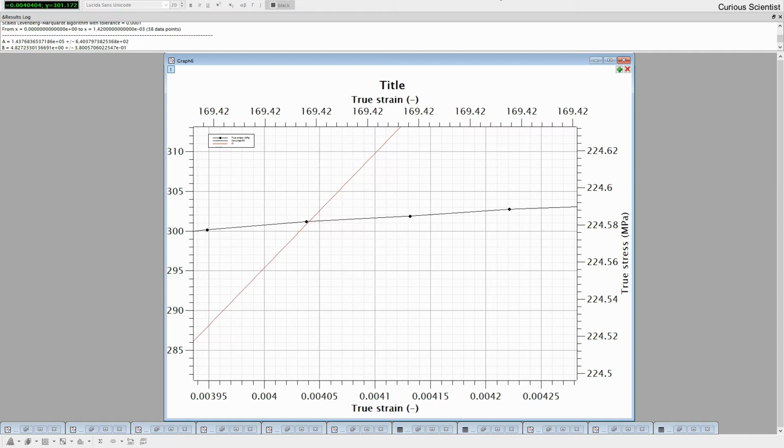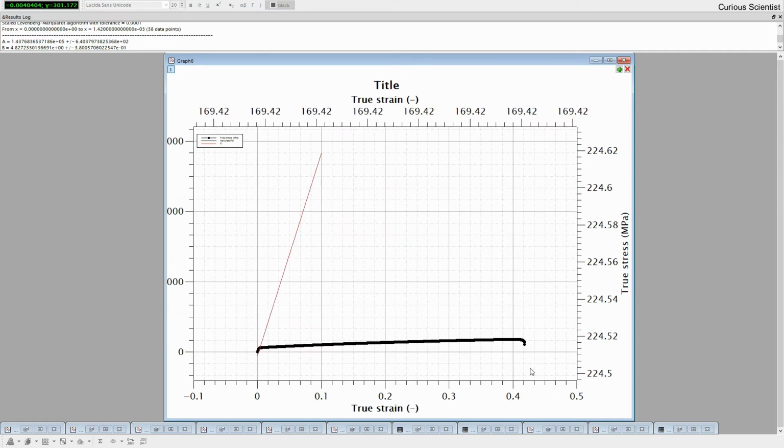So we can continue. So basically this is the second value. So we know the Young's modulus, or modulus of elasticity, and now we know the 0.2 proof stress. So now we only need the ultimate tensile strength of the material. Now I will cheat a little bit. Because there is one problem which you should know. If you have a lot of data points like me, I have like 5,000 data points, and if you try to differentiate that curve, the following thing will happen.